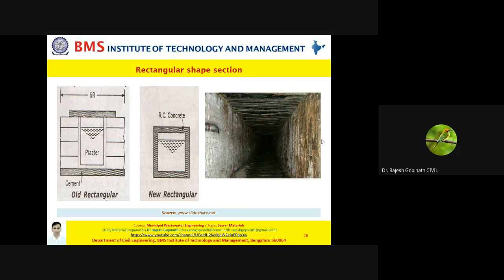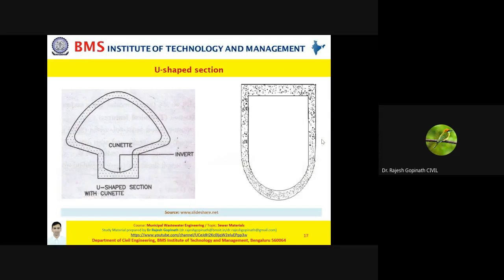Okay, fine. Now let us move on to the next one. You're now typically looking at a U-shaped section. Friends, these kind of sections are best suited for combined sewers, wherein you are able to handle maximum flow of the sewerage system, that is when you have maximum flow of storm runoff coming. These kind of sections are also best chosen when you go for long sewers.